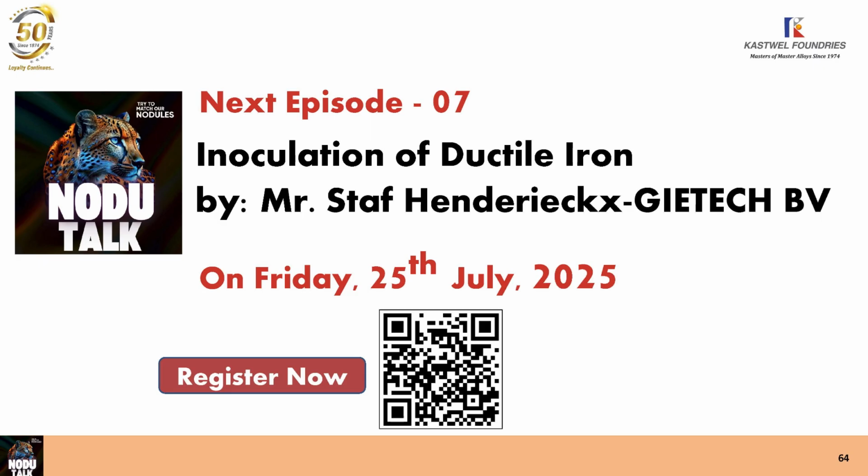Please don't ask me how to avoid it. If you don't decrease your active magnesium content, you will have dross, because the magnesium is so reactive that it will react with the silicon, it will react with the oxygen, everything it finds. The second thing is the silicon is fairly restricted.